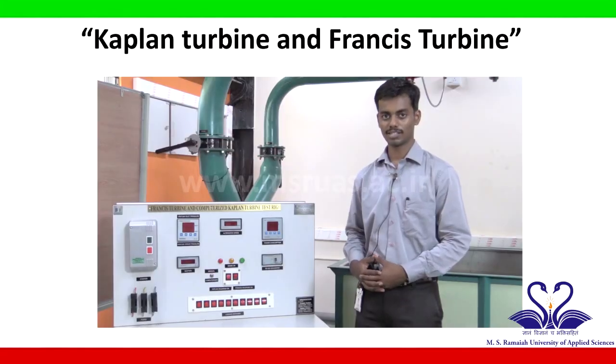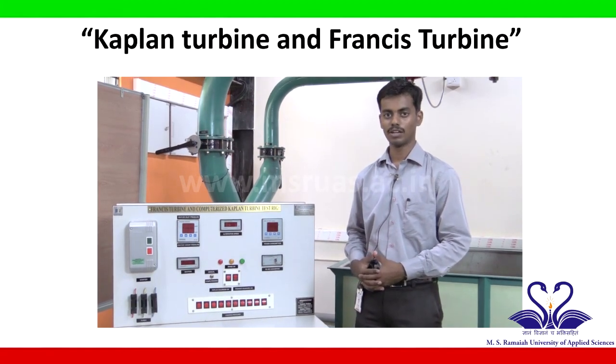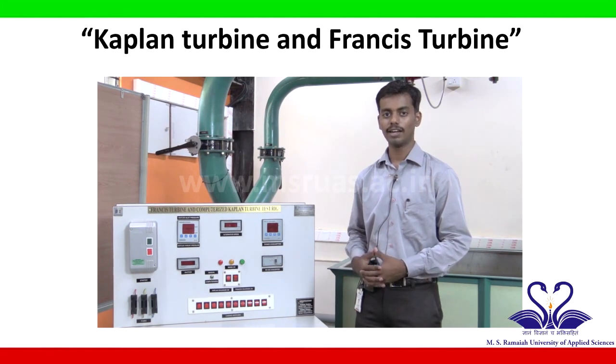Even for the Francis turbine, we shall switch on a few bulbs and load up the turbine, and hence calculate the inlet pressure, throat pressure of the venturi meter and the turbine outlet pressure, along with alternator speed and the power from the incandescent bulbs that is being extracted from the alternator.